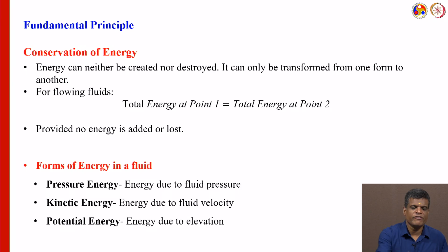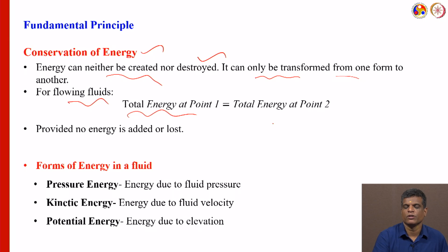The conservation of energy, the famous first law of thermodynamics, says energy can neither be created nor destroyed, but it can only be transformed from one form of energy to another. So, for flowing fluids, the total energy at point 1 equals the total energy at point 2, provided no energy is added or lost here.